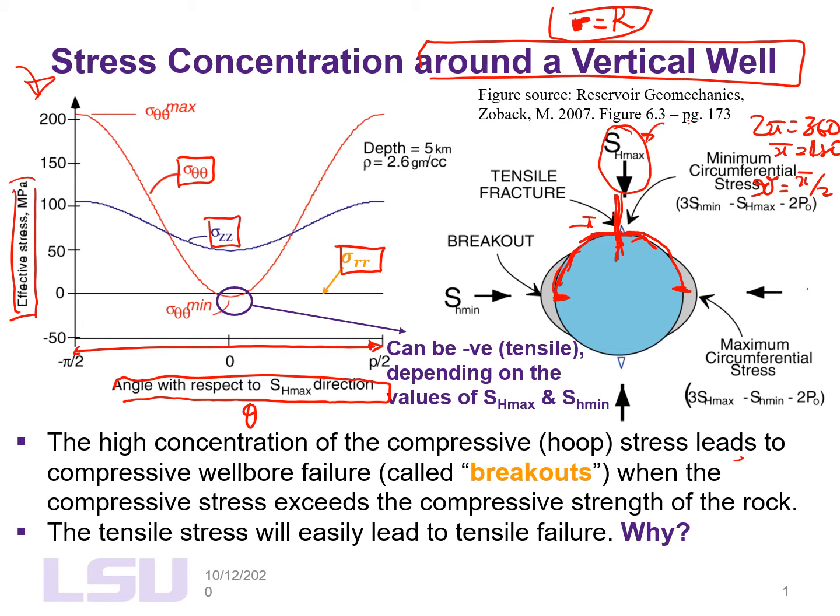And remember, there is a theta in the Kirsch equation. So just go in there and put these values of theta in, and you get different values for the 3 effective stresses, and that's what is plotted up here. And the hoop stress is the one that gets the highest. That's the one we've been looking at the whole time, and it's maximum at this value right here.